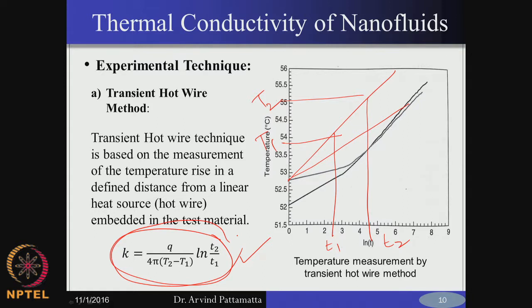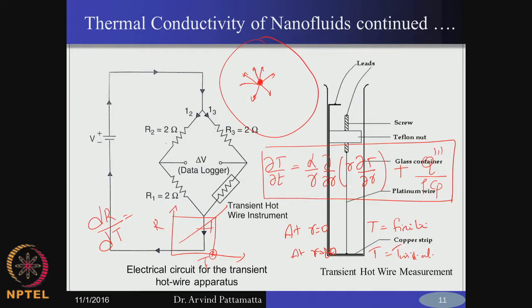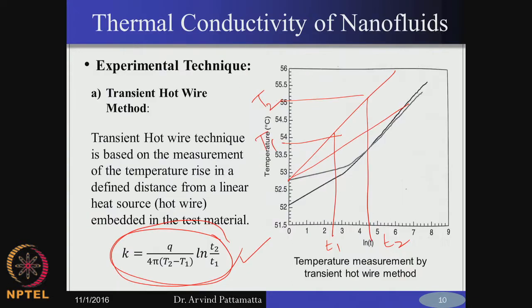That is what. So, this process itself is very fast. So, this measurement will be over in about 2 to 4 seconds. Okay. So, the actual time will be maximum 4 seconds. So, by this time there will be no significant natural convection, because natural convection takes a long time to get established. Okay. The experimental time is much faster than the natural convection time scales. So, we can safely ignore the effects of natural convection.